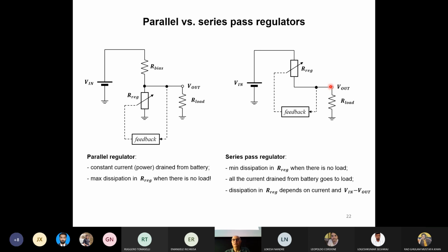So we change, thanks to the feedback system circuit, the output voltage just changing the resistance of this regulator. It's again a voltage partitioner, R1, R2. For instance, if we don't have load, we must bring R to infinite. So we open this element here, and the output voltage will be fixed. It can even go to 0.